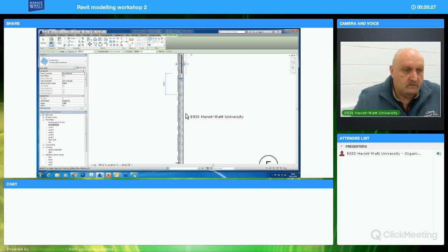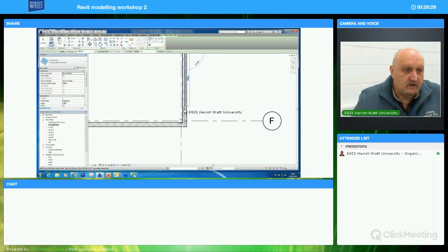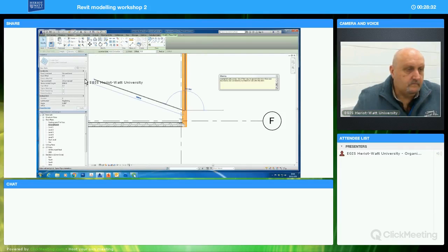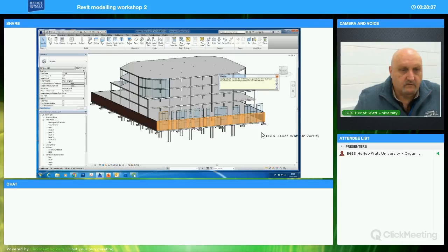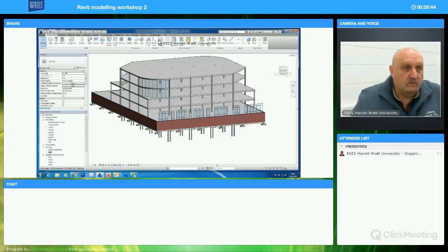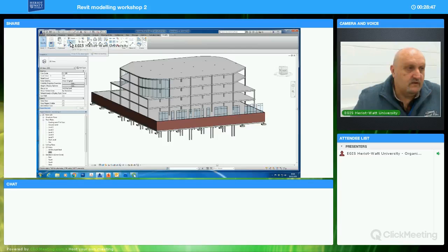Now these walls are embedded in the brick walls, you can see. And if I look at this in 3D, move that out of the way, you can see in here what we've modelled. Now you have to go to modify and then the tool called cut geometry. Usually just called cut, but it's called cut geometry, its proper name. And then you select the big wall, the brick wall, and you're going to cut it with those storefront curtain walls. And I'm going to do them all.